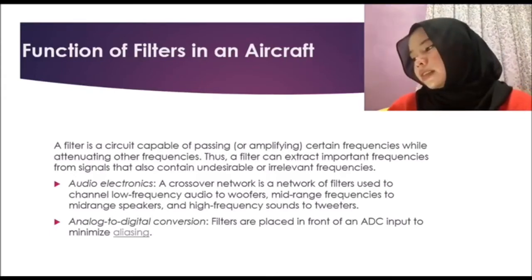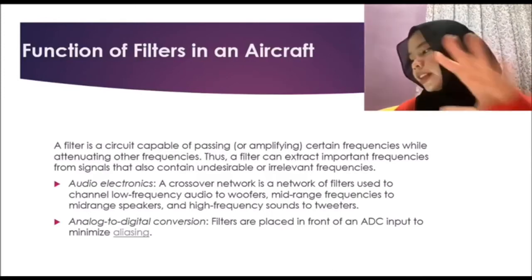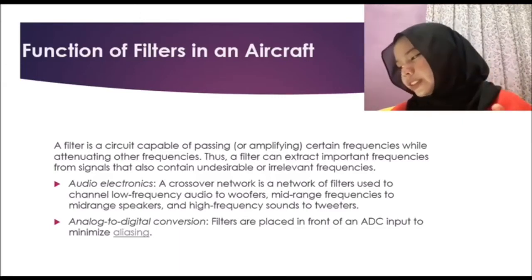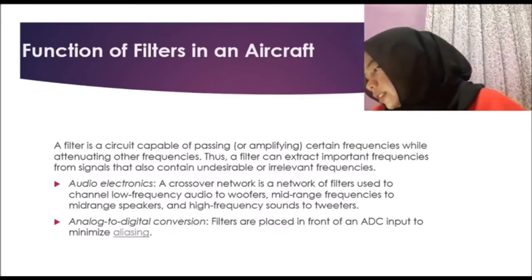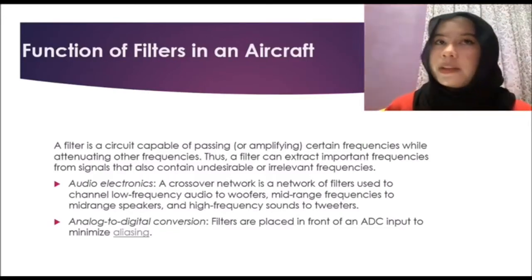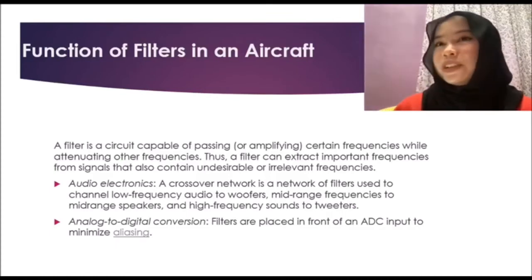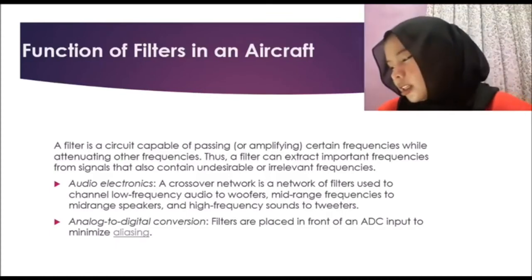First, audio electronics. A crossover network is a network of filters used to channel low frequency audio to woofers, mid-range frequency to mid-range speakers, and high frequency sounds to tweeters.